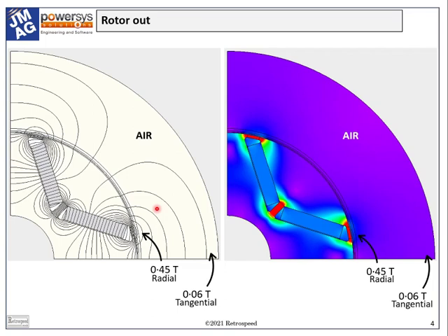And not only that, but the direction of the field changes rapidly as we move around the region surrounding the rotor. As anyone who has worked with this type of rotor will know, this means that any ferromagnetic object can easily be wrested from one's grip and smash itself against the rotor surface with violent force, quite possibly causing permanent damage if it strikes one of the bridges, and there's also a danger of personal injury.